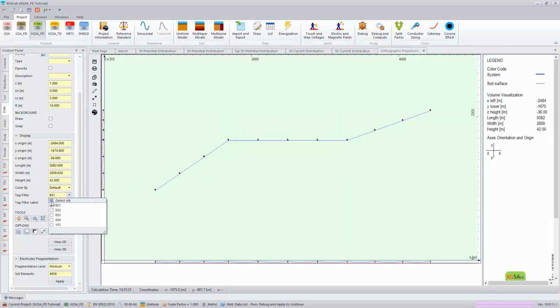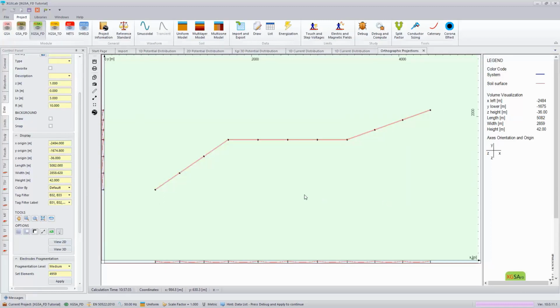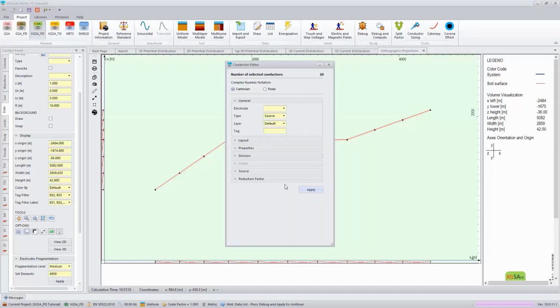Next, we're going to take a look at our other phase conductors, and we'll just zero these values out. This isn't necessary, and actually in a normal faulted condition these phases will have normal load conditions. However, we do want to match the tutorial documentation, so we're going to modify the source current on each of these other phases to be 0.